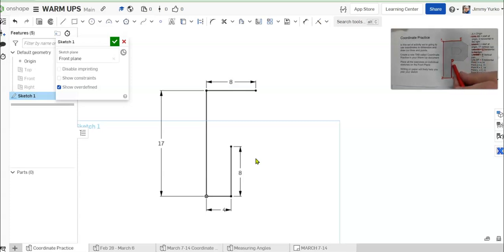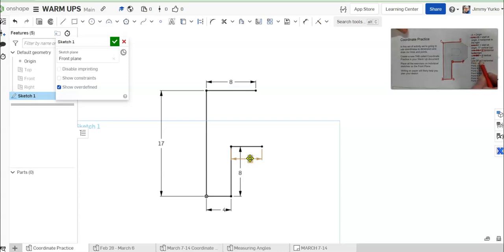Okay, check did that. Line DF. Well, that's from point D, and again, only one direction to go. So that must mean this is point F. That's 5 horizontal. So it's going to be a line across here. Line. Click and release. Click and release. Oops, forgot to put the dimension on, so no big deal. Hit the dimension tool and 5, enter. And line DF horizontal. Okay, so that's done. So I can check that off on my list.